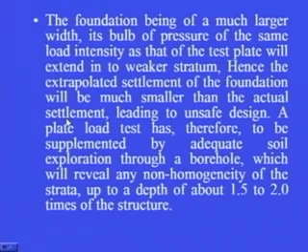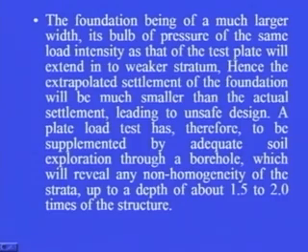The foundation being of a much larger width, its pressure bulb of the same load intensity as that of the test plate will extend into the weaker stratum. Hence, the extrapolated settlement of the foundation will be much smaller than the actual settlement, leading to unsafe design. A plate load test has therefore to be supplemented by adequate soil exploration through a borehole, which will reveal any non-homogeneity of the strata up to a depth of about 1.5 to 2 times the width of the structure.